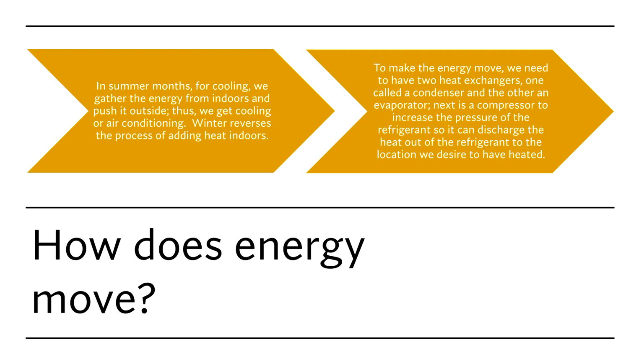The outside air is 95. Well, there's a 15-degree temperature difference between the temperature of the refrigerant vapor and the air outside. Therefore, hot travels to cold, and we reject it outdoors. We cool the indoors. We take that extra waste heat that we don't want and send it outside and give it to Mother Nature again and give it back to her.